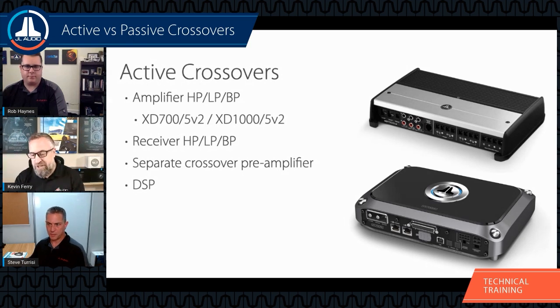Things aren't going to mesh well. You might get lucky and they work together, but play the lottery that day for you. So try to use the filters from one device. If you're using a VXI amplifier, utilize only the filters on the DSP. Keep the receiver just playing full range out of the outputs and don't make any changes from there.